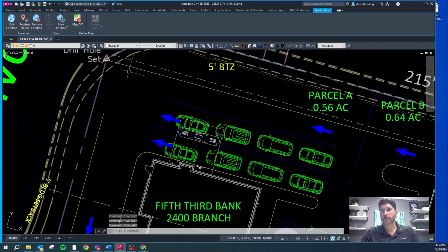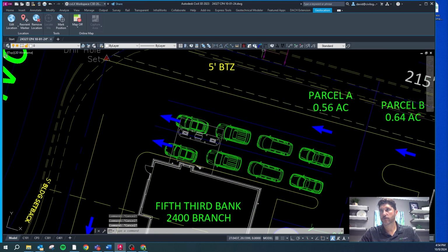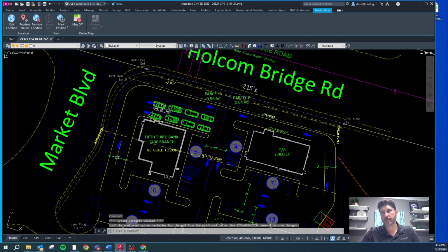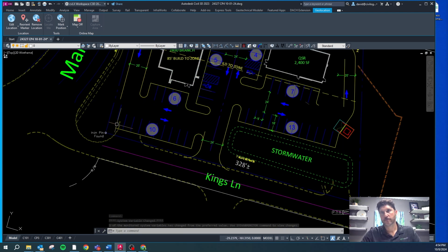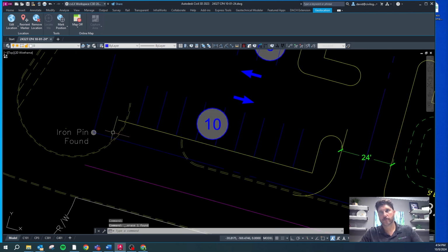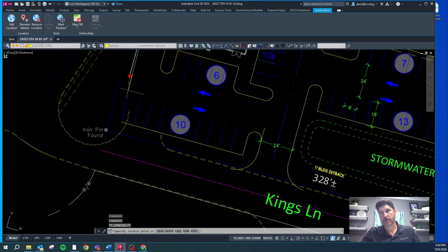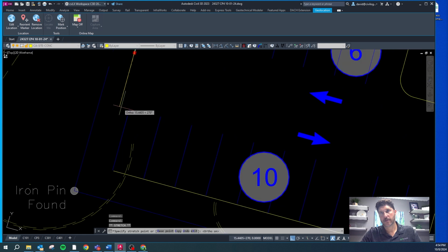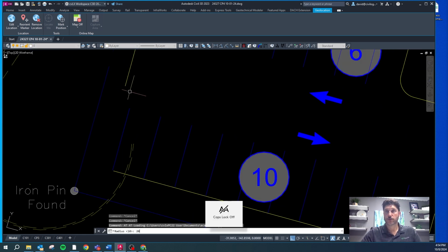And then a lot of times in these corners of parking lots, I like to use 20 as a default. If it needs to get a little tighter, I'll go to a 15, but 20 is usually just a nice curve dimension. And show you how I like to do these things. When you have this side piece that doesn't line up exactly with that, you can use AT and choose the 20-foot radius.